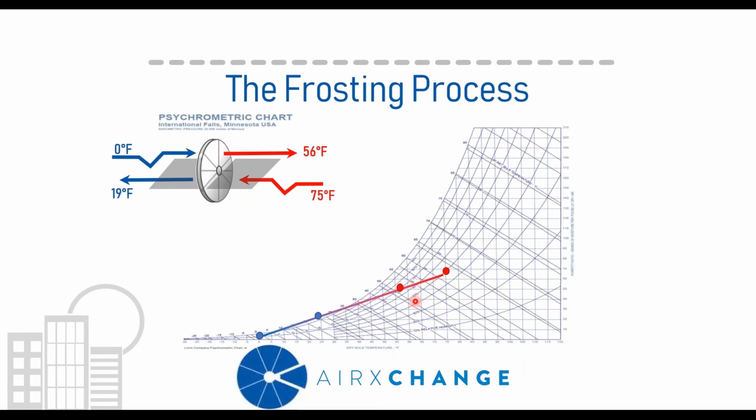Another thing that I like to point out that I've accumulated over my years here at Airxchange is, as a rule of thumb, most commercial spaces have a tendency to dry out during the winter months. So in a practical sense, while the design may have started with a high relative humidity, the actual operating condition might be quite lower than that.